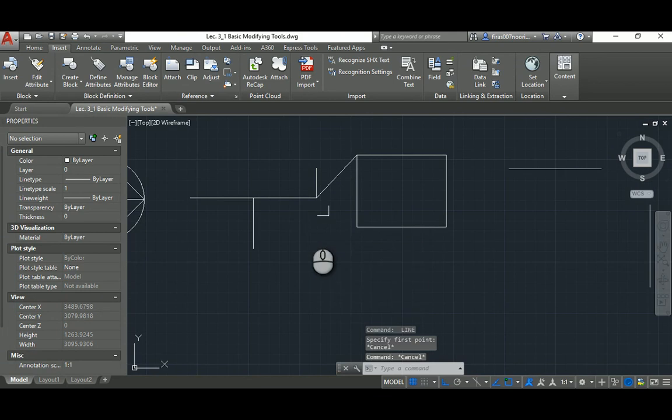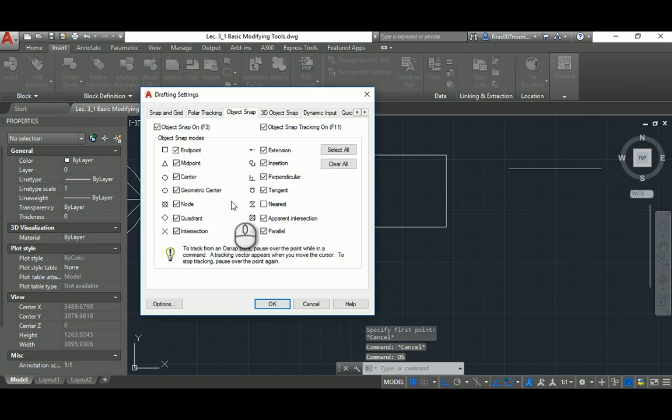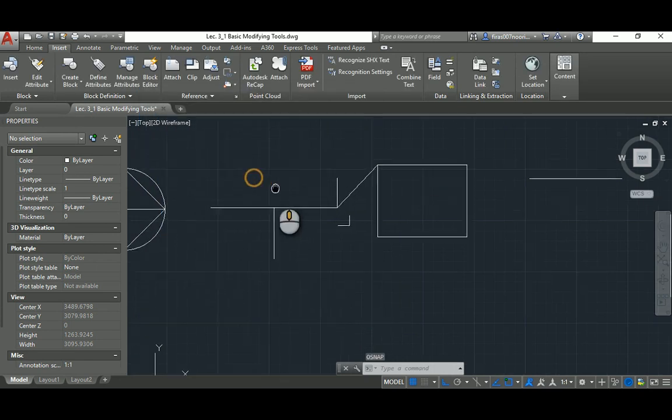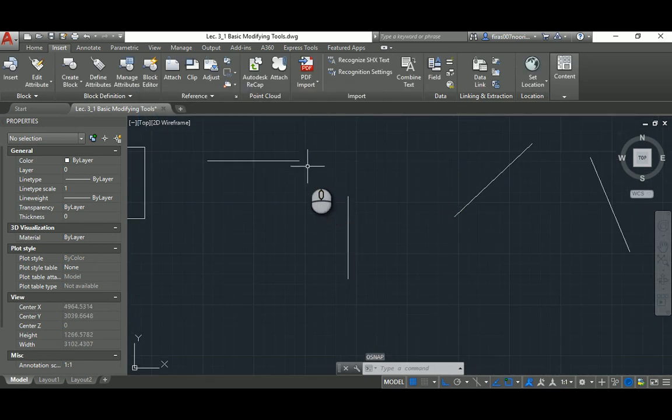Now another useful thing is to understand that you have the ability to extend lines in an imaginary condition, depending on this option here, extension. So physically, if you have two lines like that that don't meet, I can sense or draw based on their hypothetical intersection point without the need to actually fillet or extend those lines. If I put the mouse at the end of this line and then remove it, you see this green tick to identify that AutoCAD extension is now active.